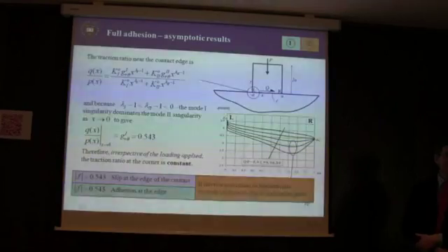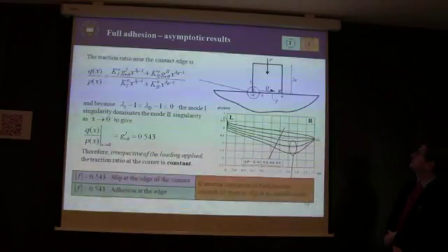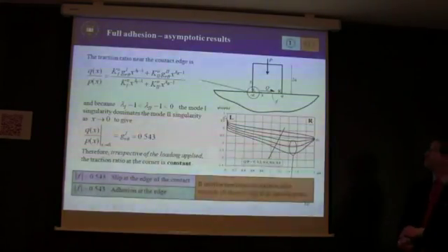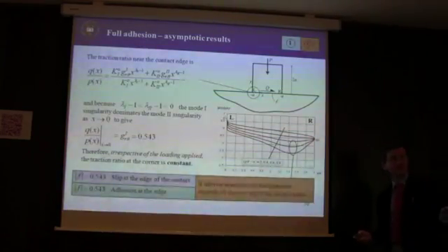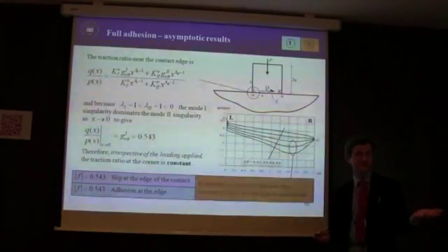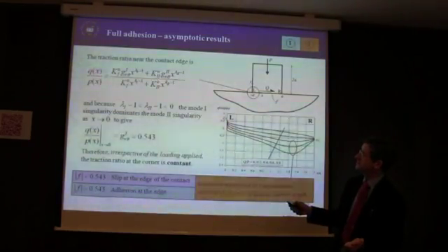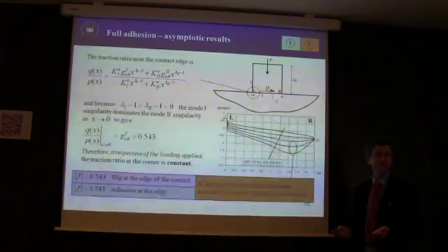So now let's think about this problem of pressing a block down on another large plate with a force P, and possibly shearing it as well with a shear force here Q. And suppose that we're interested in these corners, of course, and that we get closer and closer to this corner here. As we do that, we'd expect, assuming it is sticking, the Williams solution to be satisfied, to quantify what's going on. And so the ratio of the shear traction to the contact pressure is just the ratio of these two terms that I showed in the last slide.